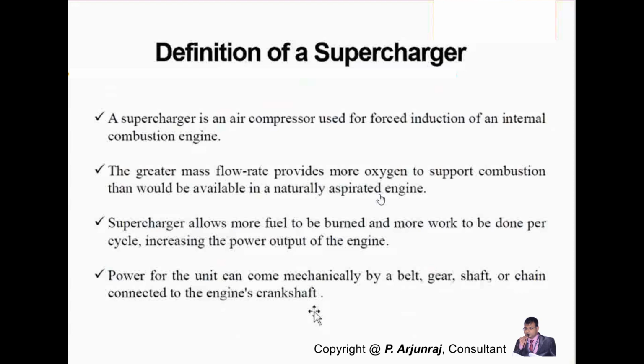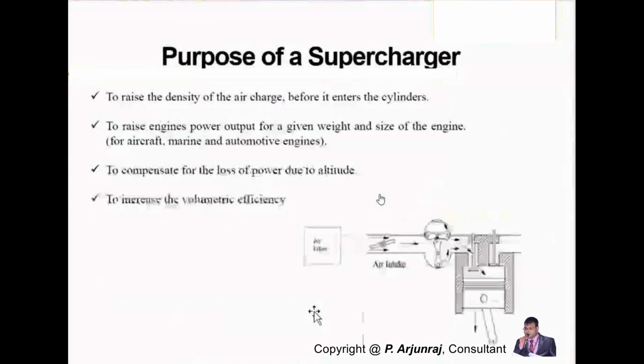So here, this supercharger will get its power from the engine itself. You are going to connect the supercharger with the help of a belt or a gear or a shaft or a chain to the engine crankshaft, and you're going to get the power mechanically.